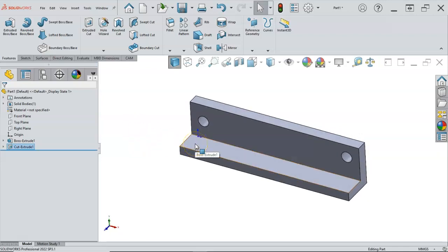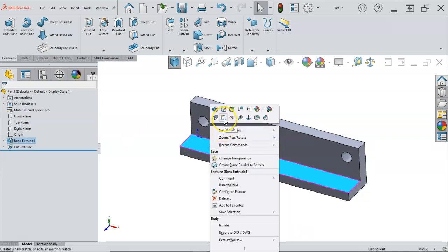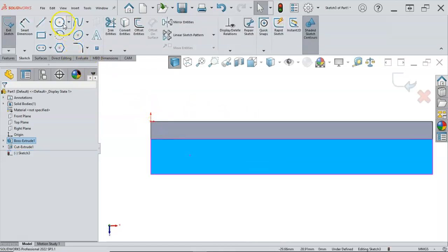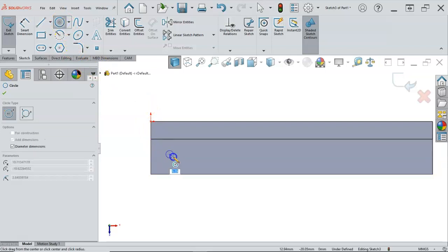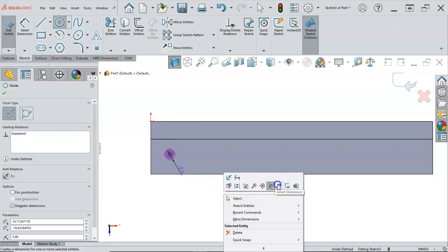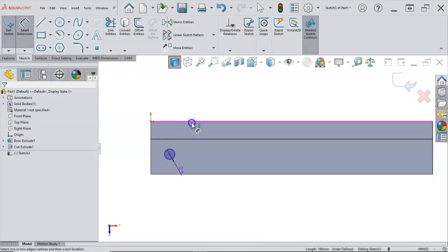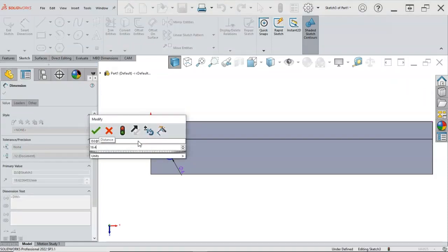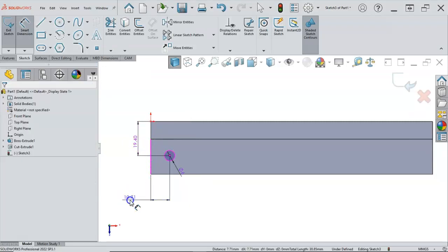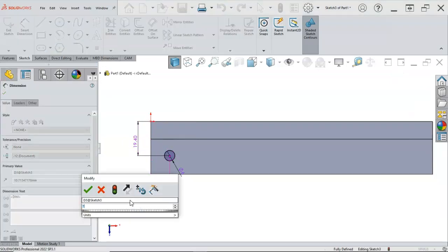All right, so on the sketch, we'll go in, right click on the face, go into the sketch, it rotates into the view. Decided that these were 6 millimeters, so we just drop it in place, add the 6, and then we have a dimension of 19.4. And from the end of 7.96.